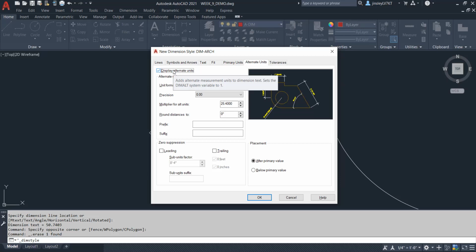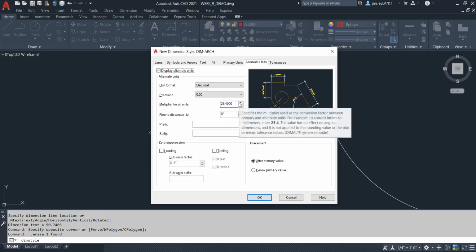Okay. So you wouldn't be able to build off of alternate units. You can't build properly off of scaled units. If you were doing an imperial project, everything would be imperial. If we decided halfway through to switch to metric, we would have to redraw that project to metric units. You can't just scale the drawing because the scaling will get you close, but it doesn't work out properly. Okay, so you have to be very, very careful about that.